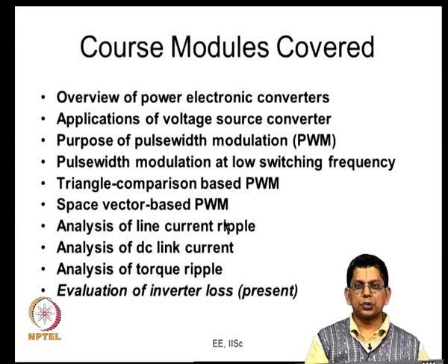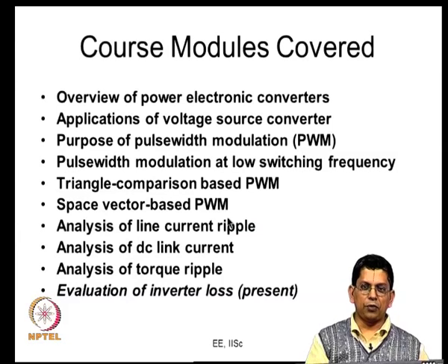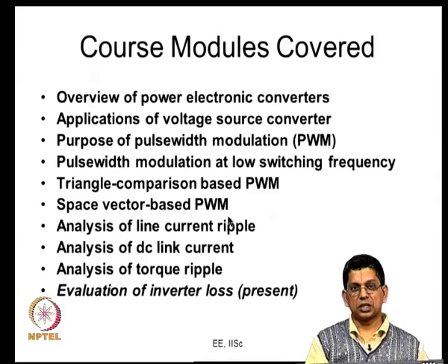These advanced bus clamping PWM methods result in bus clamping just as the discontinuous PWM methods do. A phase would not switch in some region of the fundamental, it would switch at the nominal frequency in certain other regions, and it would switch at double the nominal switching frequency in some other regions. So, these are advanced bus clamping PWM methods.